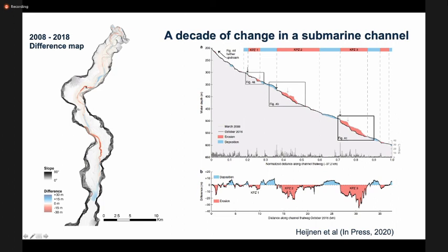So here we see elevation changes of up to 30 meters, and we see down from the lobe deposition, but also these cyclic changes in erosion, deposition, erosion, deposition, erosion. And Martin's looked at a series of these repeated seafloor surveys to document how the seafloor is changing. And yes, we see a bit of outer bend erosion. Yes, we see evidence of upstream migration of crescentic bed forms. But what dominates the erosion and the deposition are like waterfalls under the sea.